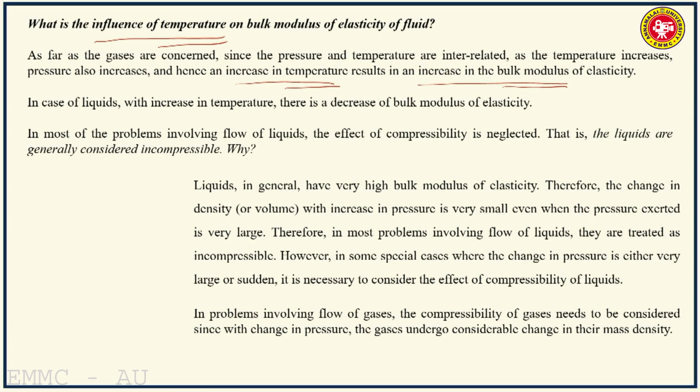Whereas in case of liquids, with increase in temperature, there is a decrease of bulk modulus of elasticity. Now, ordinarily the liquids are considered incompressible. So, what happens with increase in temperature? The molecular activity increases, the molecules become widely spaced, and therefore the bulk modulus of elasticity may decrease.